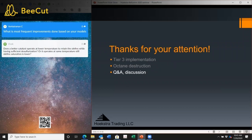So if you have a catalyst like maybe cobalt molybdenum catalyst instead of nickel molybdenum, or which is activated by maybe vanadium or something other, it will probably hydrotreat easily the sulfur removal, but probably not do the aromatic saturation. Only olefin saturation will take place. That's my understanding. I don't know if you have some comments on that.